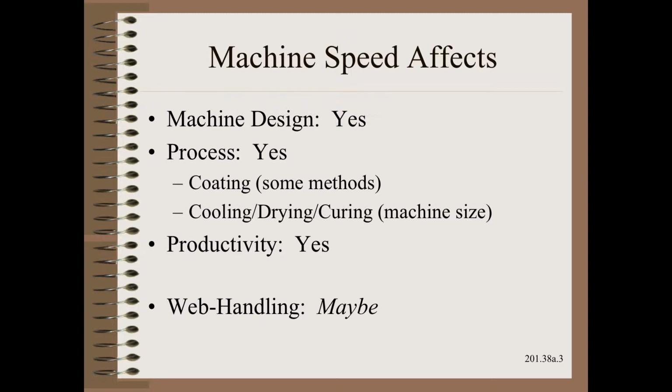So let us begin with what should be the best understood factor in web manufacturing, web converting, and web handling. Of course, speed affects machine design. However, most of the effects have to do with drive sizing and the automation of the front and back ends of a line. On the other hand, the effects of speed on web handling mechanicals is usually quite small, such as RPM ratings of bearings, until you get to higher speeds where air entrainment and vibration come into play. Of course, speed also affects some manufacturing and converting processes, sometimes quite profoundly.